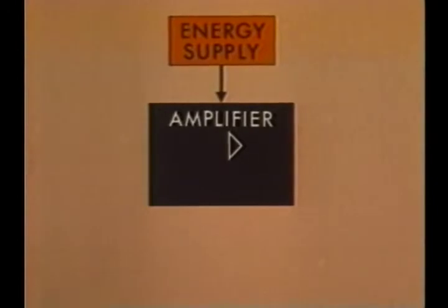These disturbances contain all wavelengths, but only a certain range of wavelengths are amplified. We can picture the mechanism of flow instability as a frequency-selective amplifier and picture it as a black box, although this is really oversimplified. An amplifier needs an energy supply. This amplifier takes its energy from the airstream. The amplifier input is any disturbance that happens to come along.